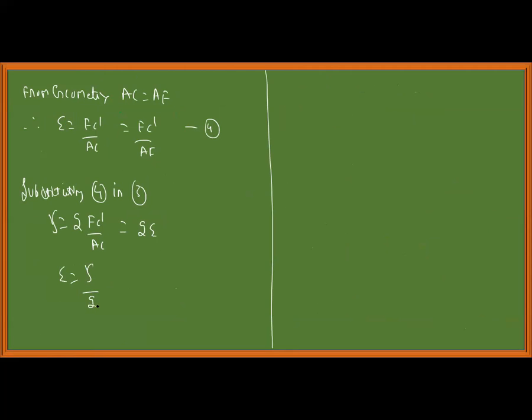When I subject the parallelepiped to shear stresses, the diagonals are subjected to linear strain, which is of magnitude half of the shear strain. This is positive along the positive diagonal. Similarly, for the negative diagonal, it will be minus gamma by 2.